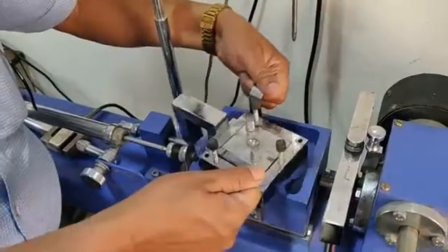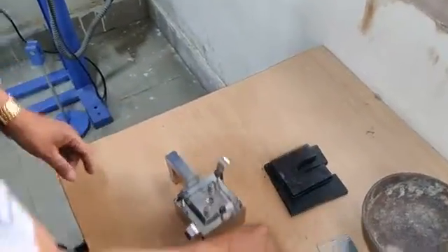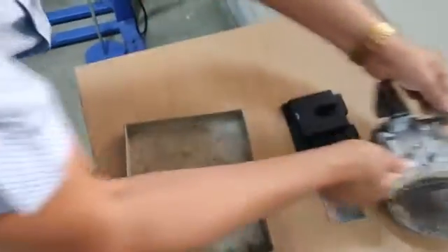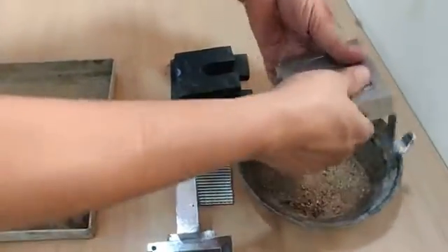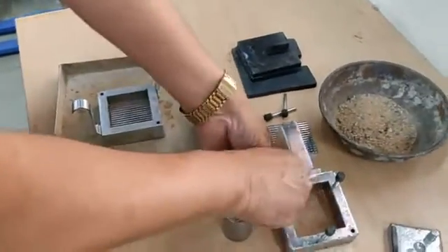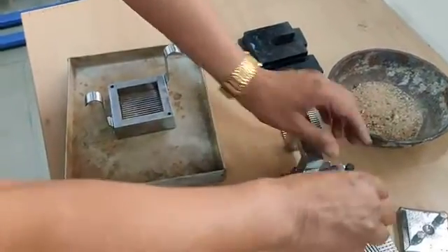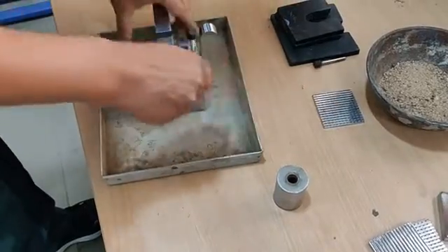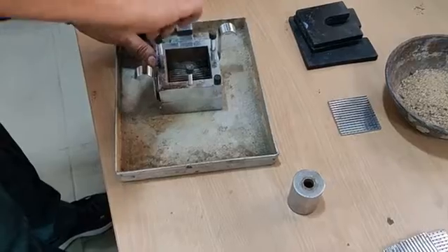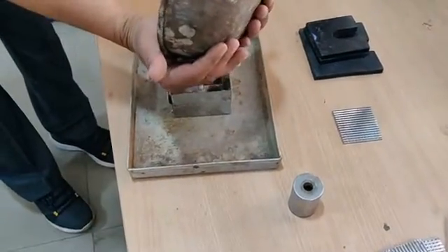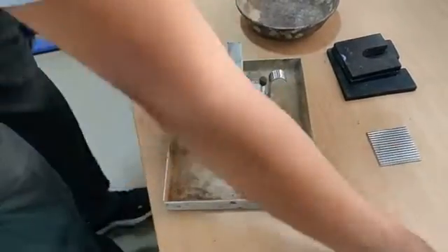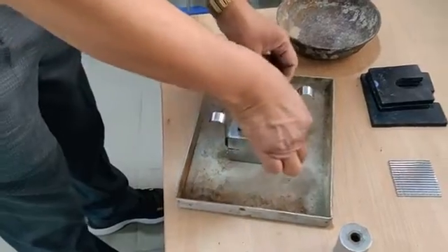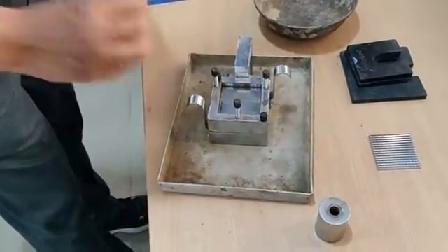So now we are going to take the sample out, and we will fill the sample again in the similar manner that we have done earlier. Now we will remove all the plates, and we will remove all the sample from this. We will take this again and perform the test in a similar way. How much soil we have to take depends on the density at which we want to perform. If we want to perform at a higher density, then we have to take more weight of the sample. And now we are going to put these two plates back into this.